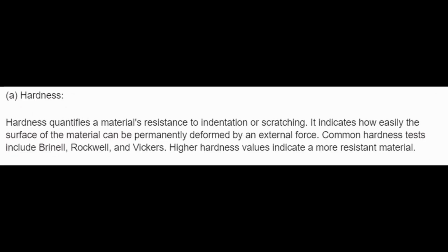A. Hardness. Hardness quantifies a material's resistance to indentation or scratching. It indicates how easily the surface of the material can be permanently deformed by an external force. Common hardness tests include Brinell, Rockwell, and Vickers. Higher hardness values indicate a more resistant material.